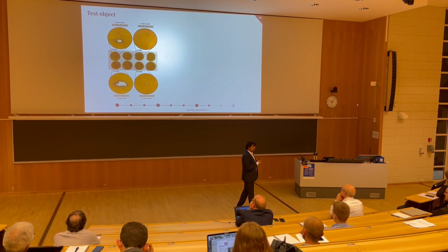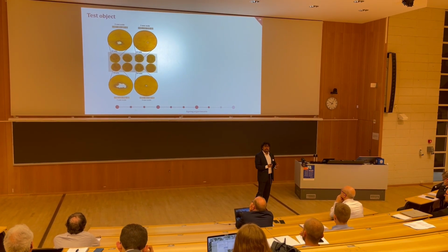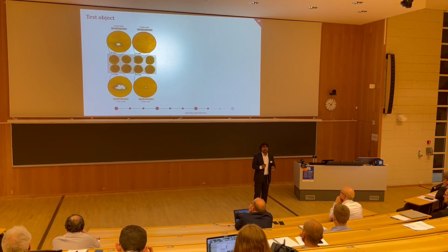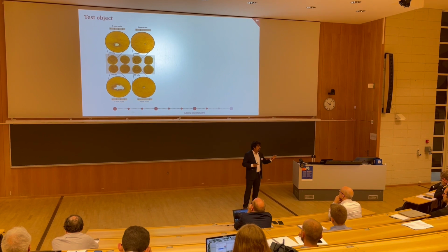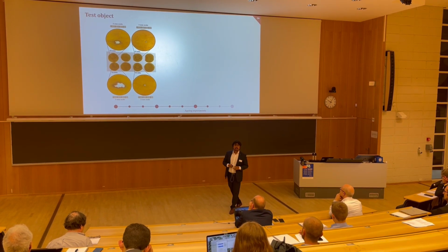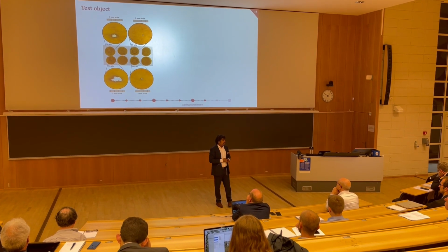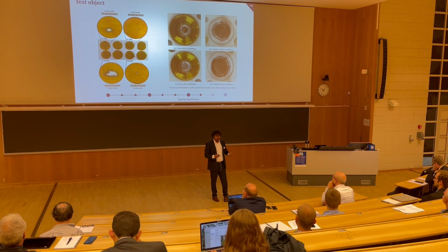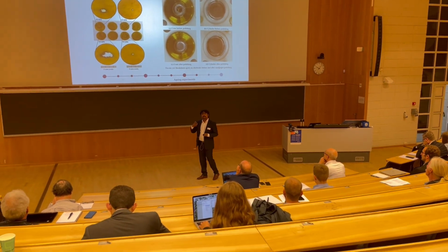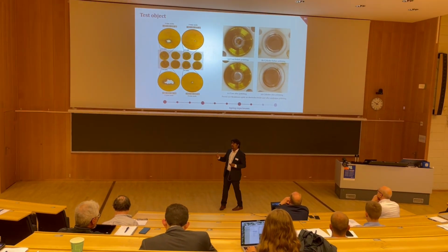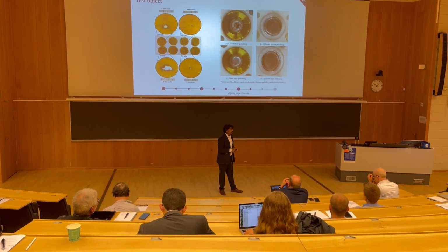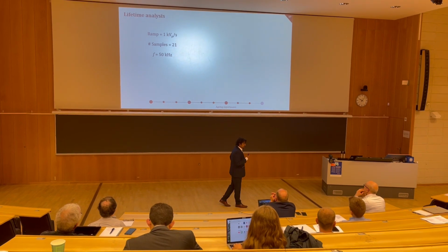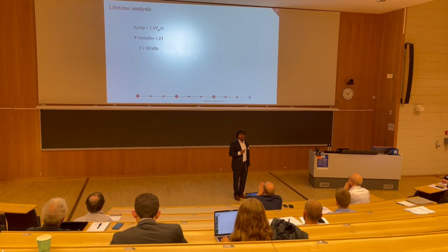Then we had to tune the sensitivity of the pulse modulator to make sure that it's breaking at the right moment. And if you didn't break it at the right moment, you would have these aggressive burn patterns. With these aggressive burn patterns, we also had to keep polishing the electrodes after every single test that we performed. The first test that we did was a ramp breakdown.